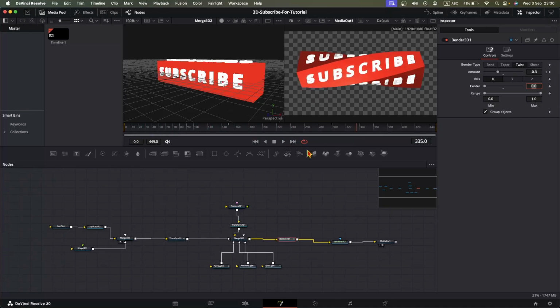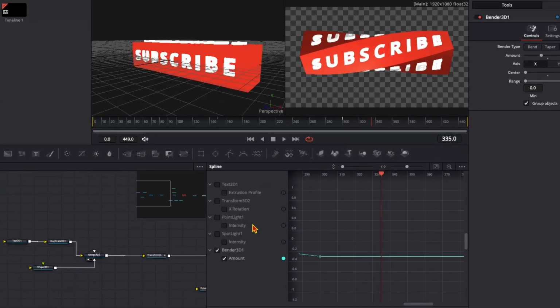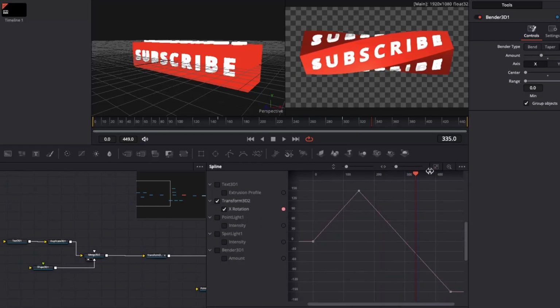The last thing to be done here is to smooth all the animation we did so far. To do that, we have to go to the spline editor. Now here you will see multiple animation we have done so far. We will go one by one. So the text 3D extrusion profile, we don't have to do anything there. Let's first unselect this and go to the transform 3D X rotation. Click here to show it all in this window.